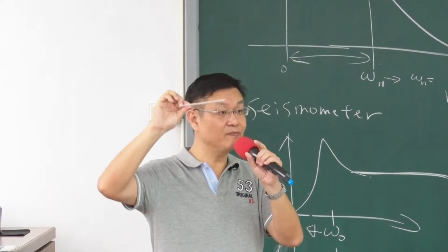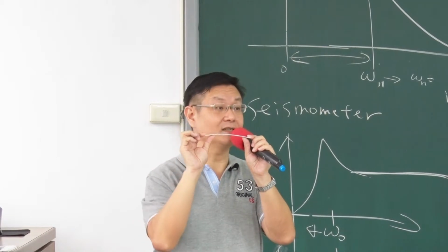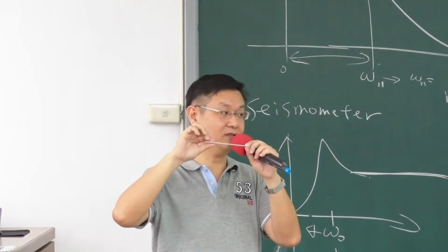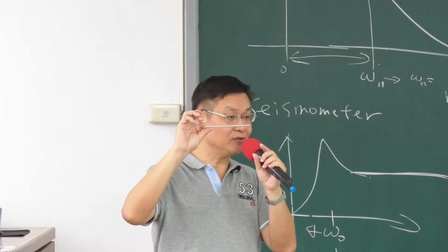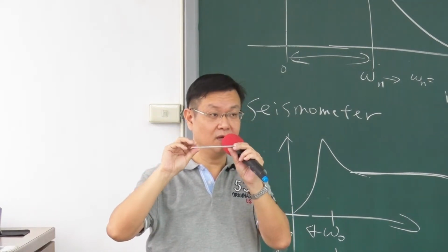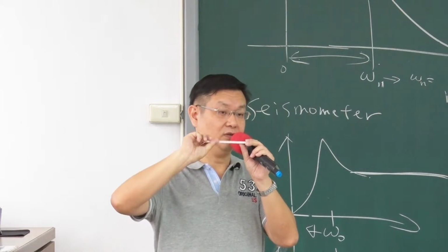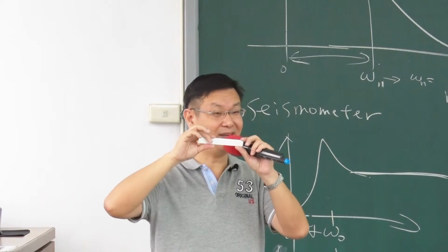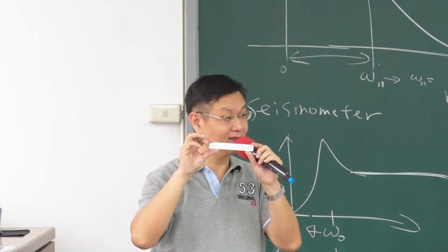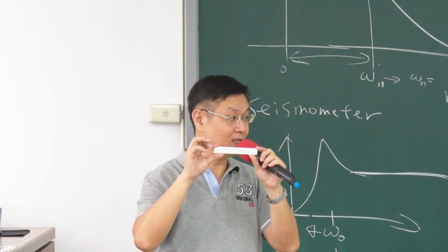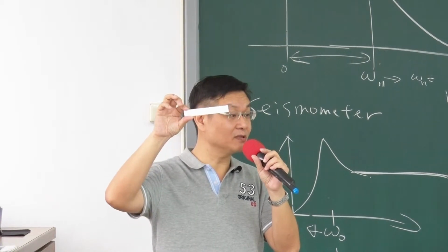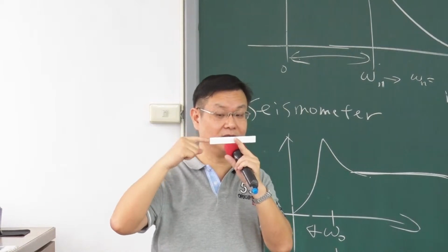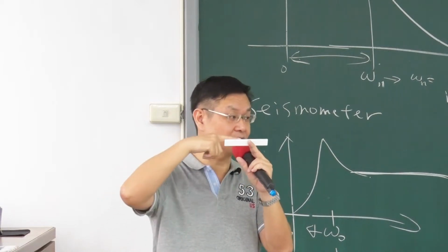For example, if you bend the ruler in this direction, it's easy, right? Because all the material is at the center, it becomes a very thin structure. So the moment of inertia in this case is small. But the same structure, you turn it 90 degrees to upright. Now you bend it again. Is it easy or not? Not easy at all. Why? Because it increases a lot of moment of inertia. The I increases a lot because all the material is far away from the center point.